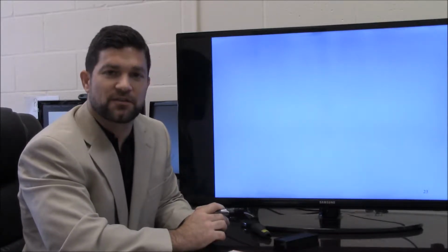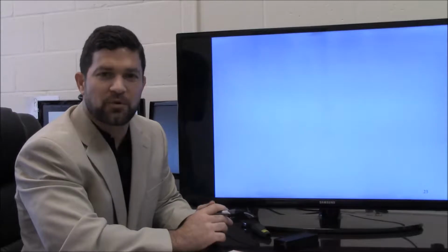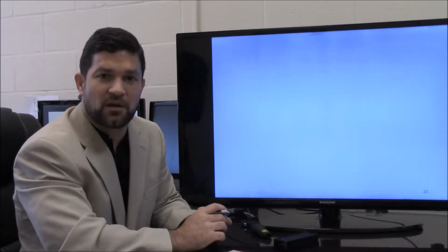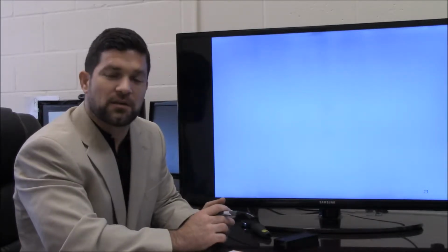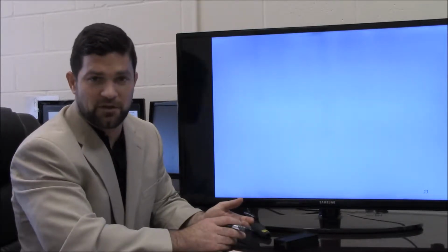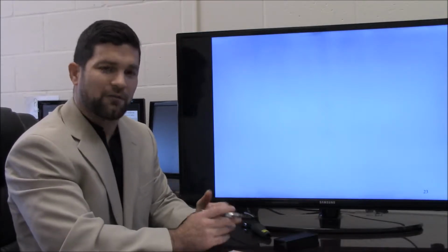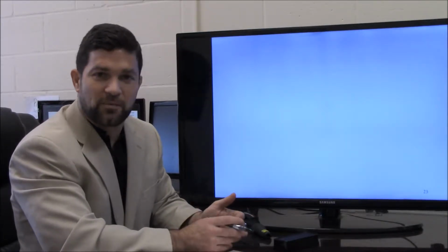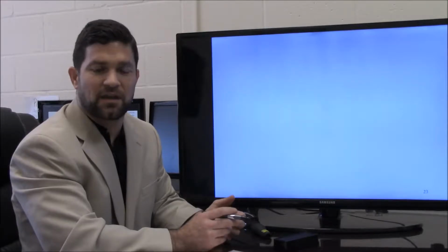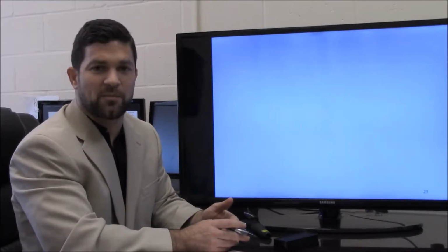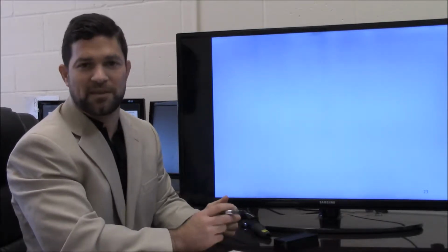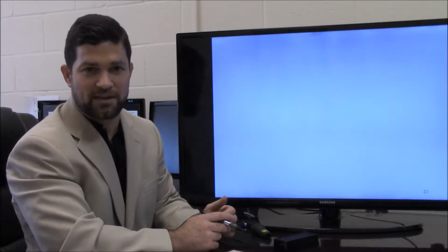For linear globe valves, CV versus percent open is pretty easy. It's going to be based on the valve size. And based on the valve size, you can get CV max, which is the maximum valve coefficient when the valve is entirely open. For our class or for other purposes, you can typically use a CV max that you get from a table that may be given for equal percentage valves, and we'll get to that in a second.